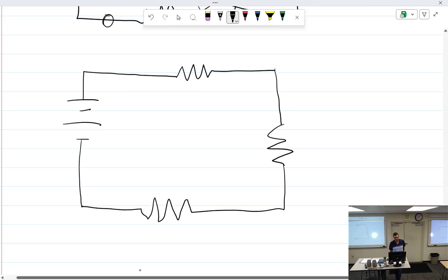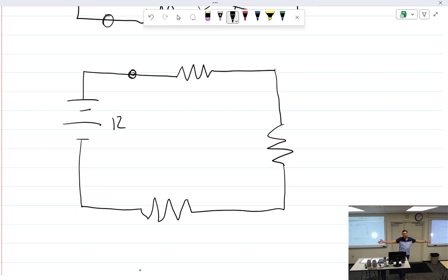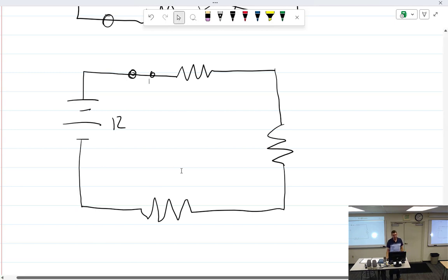And as we talked about earlier, if we examine this spot right here, this is a 12-volt battery, how many volts are right there? Compared to what? It's like, I don't know. How many volts are right there compared to right here? 0. That's a hard concept for people. It's like, so you mean there's no pressure there? Well, yes, there is pressure there pushing electrons through, but you're not comparing it correctly. So the question is, there is pressure, but compared to what? Compared to right here, well, then there's 12 volts of pressure.